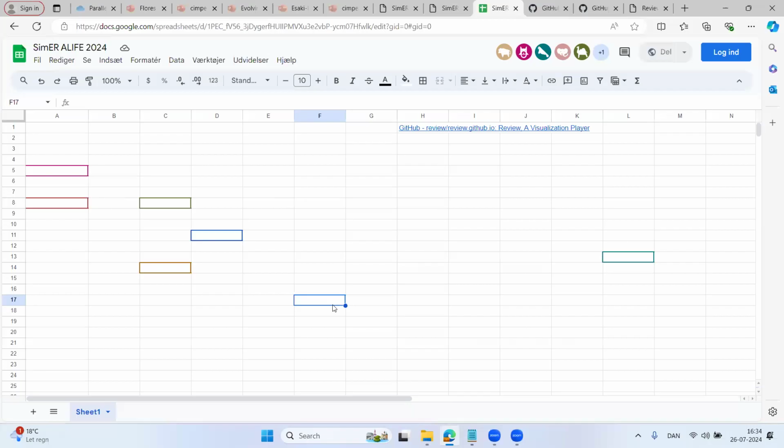They get a constraint value. If they're really bad, the wheels overlap by a lot, meaning you couldn't construct it, it gets a really bad mark on feasibility. That gives you a gradient for pulling those two wheels apart, either by making them smaller or making the chassis wider. It gives you a gradient from something not feasible to something feasible, as opposed to throwing it out and giving it a 0 objective score.